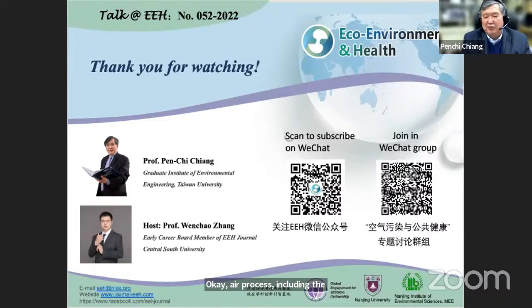and carbon dioxide. Usually, the traditional technology to reduce air particulates needs a cyclone, wet scrubber, baghouse filter, or electrostatic precipitator. So this is one. And for NOx reduction, we need to provide DeNOx. And for SOx removal, we have to provide flue gas desulfurization.